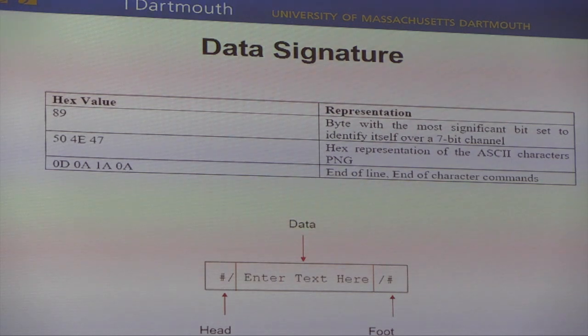So in our example, we have this symbol right here, the # signifies the head of the data, and that in reverse would signify the footer, or the chunk at the end of the data. And we're basically looking in our script for the payload in between those two. So whatever's in between these two signals, we know that's our data that we want to see, and we want to pipe that straight into the console to view when the user is receiving information on their USRP device.